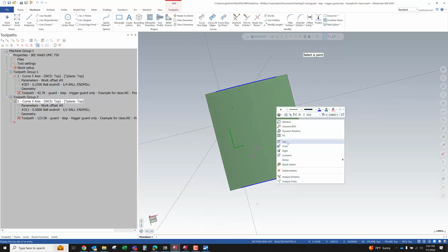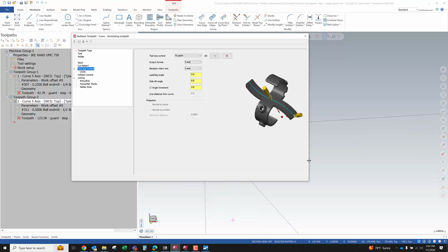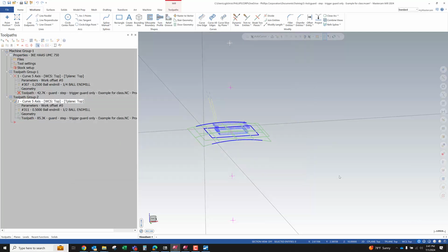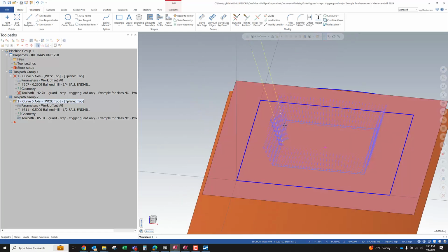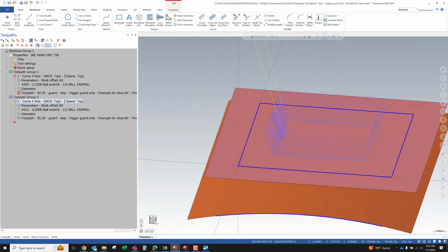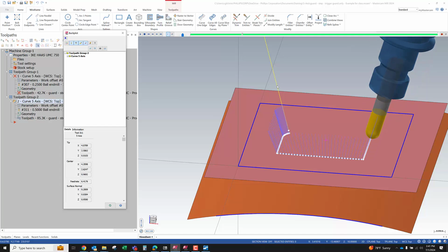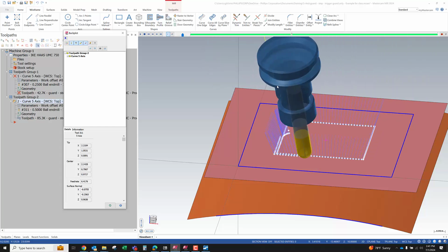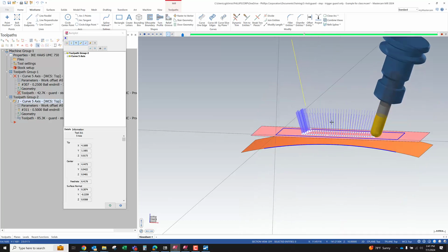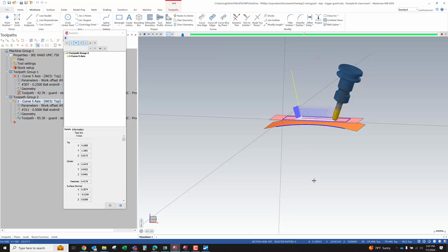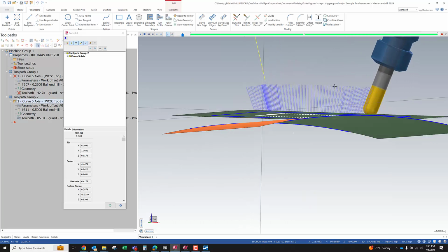Let's look at the top view. Okay, it should be right in the middle. It's the 2 point. There it goes. Now it's generating. Okay, so exactly the same path, but we just changed from a from point to a 2 point. So now it's rotating where it's always trying to keep the center line of that tool focused at whatever tool. And because I chose this point, which is only 5 inches deep instead of 10 inches deep, we get a more extreme angle.